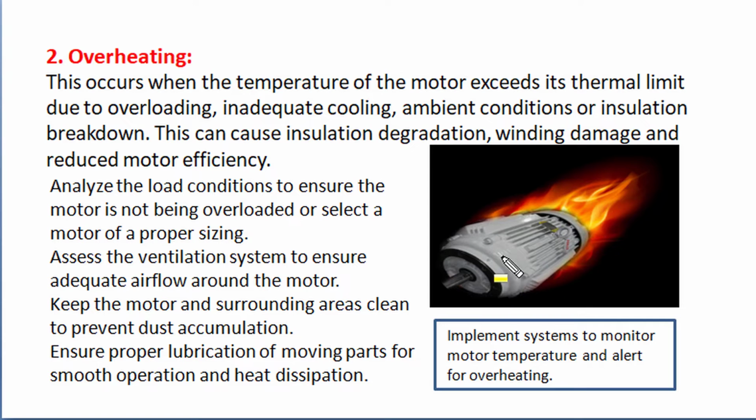Now, to safeguard a motor against overheating, it is necessary to analyze the load conditions and to ensure that the motor is selected of a proper size, and during operation it is never overloaded. We also have to assess the ventilation systems to ensure adequate cooling airflow around the motor, and for that we have to keep the motor and its surrounding area clean, and prevent all sorts of dust, dirt, or other accumulations. To reduce friction and unnecessary mechanical loading, we have to ensure proper lubrication of all moving parts for smooth operation and cool operating conditions.